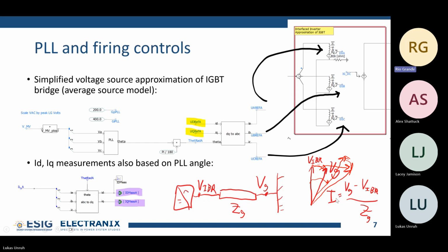And this also gives an idea when we start talking about weak systems. This controller works very well when the grid angle is not particularly influenced by the amount of current that we're injecting onto the system. When the grid angle is severely influenced by the amount of current, that's when we can start running into weak system issues. And that's when we can say the grid is no longer stiff, because that system angle starts to vary a lot based on the amount of current.